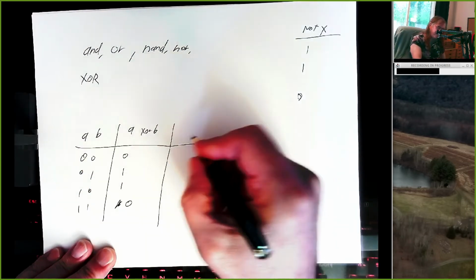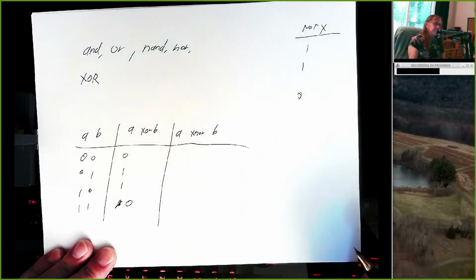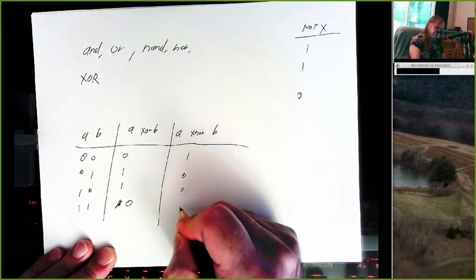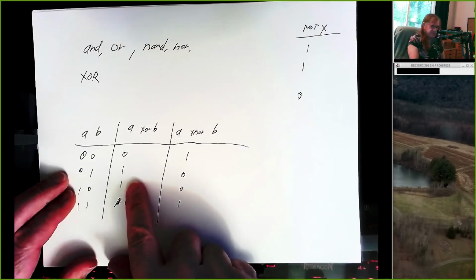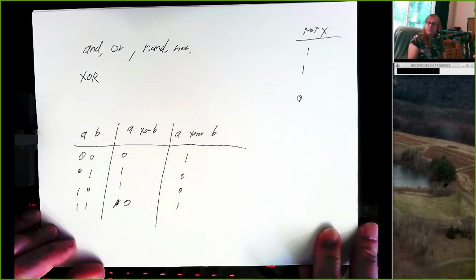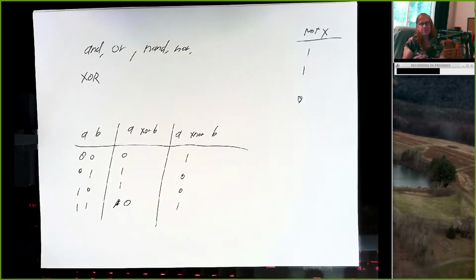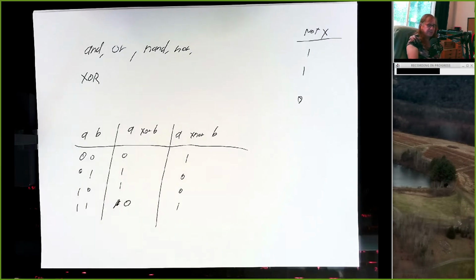And we can have the opposite of this, which we call an exclusive NOR, so xnor, and that looks like this. Yeah, so this is also saying, do we have an odd number of inputs that are 1? Which ties into something called parity, which we'll talk about later, and we'll talk about in 270. And so it tells us, do we have an odd number of 1s, or do we have an odd number of 0s?